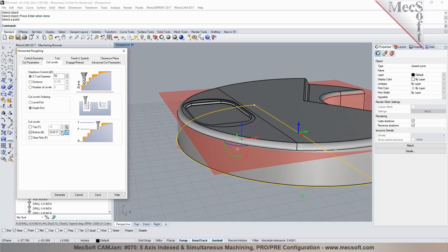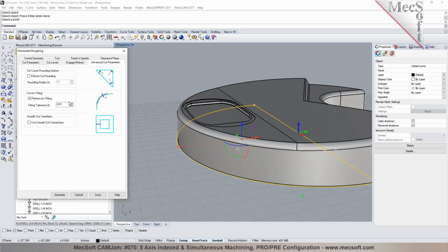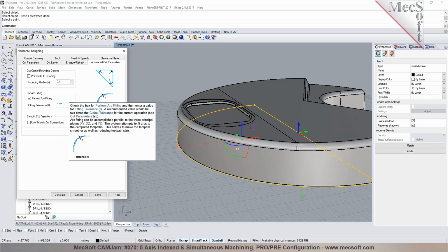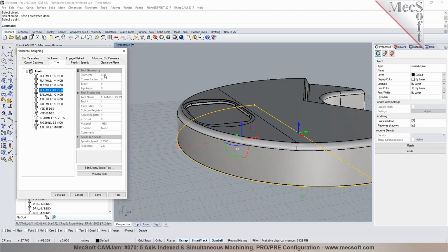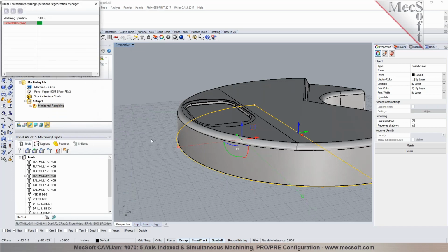One quick question. The CAM file, does it talk to the computer, talk to the CNC to know where to pick that tool up from? We output a tool number like a T followed by the number and then M6. So basically that tells the controller to go grab the tool number. So when you have an automatic tool changer, it'll just go grab it from there. So all you need to do is make sure the tool numbers are set correctly in your program to match the location of where the tool is on the machine tool.